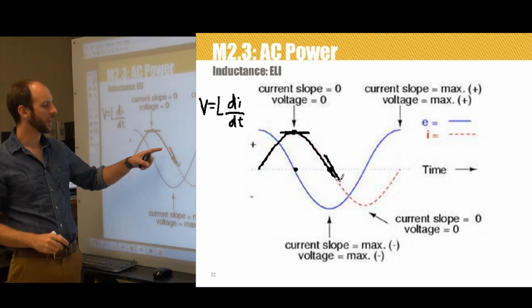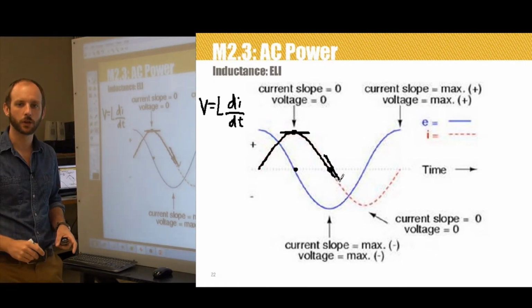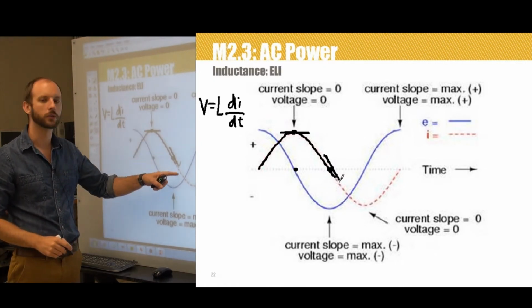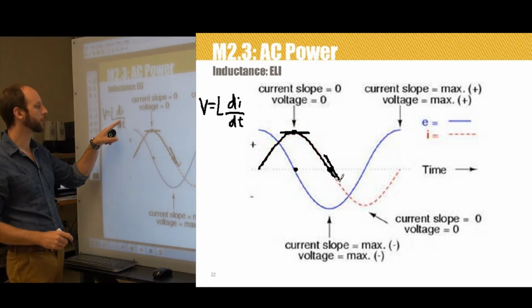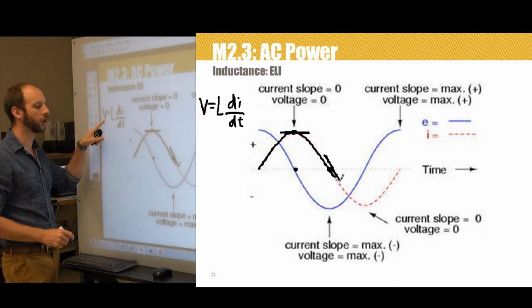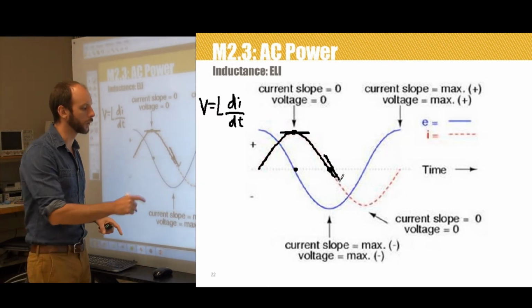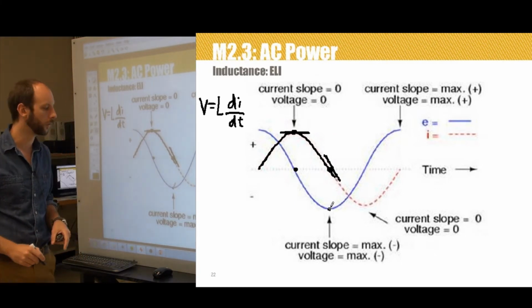You'll also notice that the current is decreasing. Therefore, that's a negative slope. It's a negative rate of change. The values of the current are getting smaller, so we get a large negative number for di/dt. Multiply that by L, and that's going to give us the largest negative voltage when we go from positive to negative across that 0 crossing. We get a large negative voltage.